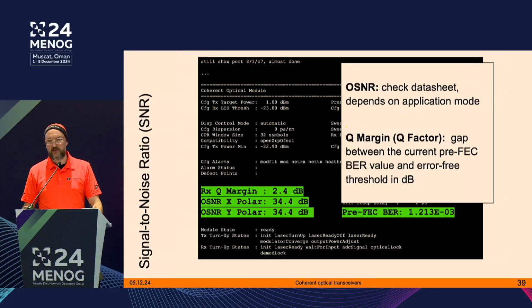So this DSP has a couple of functions. The major function is to generate the modulated signal, but it also can correct errors when there are errors on our transmission, and that's called the forward error correction. So we add a little bit of overhead to our desired signal, and then we can detect the errors while they are on the line or when they are hitting the receiver, and we can even correct them.